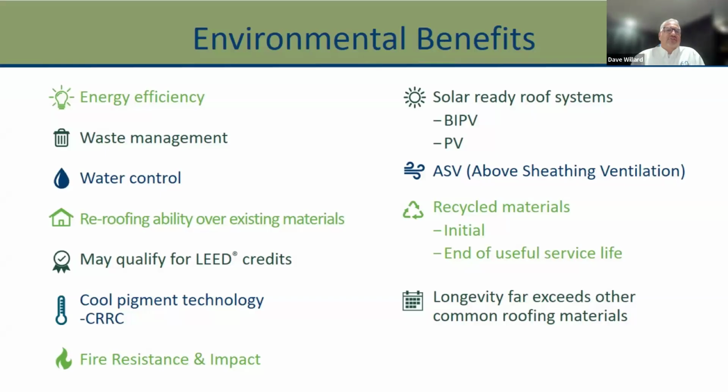We can talk about energy efficiency, water control, which we'll talk about towards the end here, cool pigment technology in the paint, ASV shims, above sheathing ventilation, and of course the recycled material from beginning to end, and the fire resistance idea. So there's a lot of good benefits that go with using metal. They are energy efficient, they can be recycled, and metal is great for applying cool roof principles, which we're going to talk about in just a second.